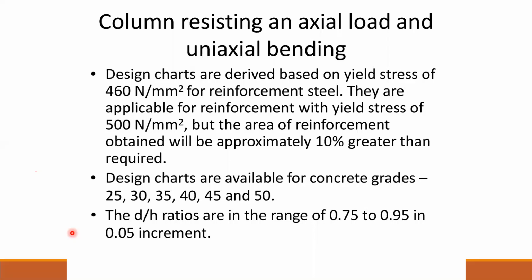So still you can use the same, but make sure that you have created the appropriate chart and referred to the appropriate chart. The d over h ratio range is 0.75 to 0.95 with a 0.05 increment. So what does that mean? When you select the column sizes, always you need to keep this d over h ratio 0.75 to 0.95.